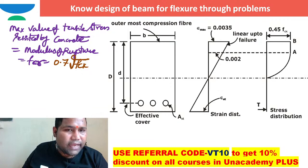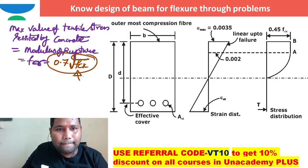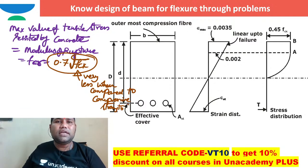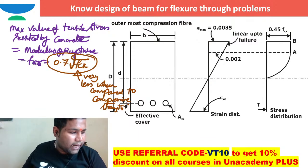So I can say this is very small compared to compressive strength, right? So based on this reason, the tensile strength of concrete is neglected and kept as zero, right?